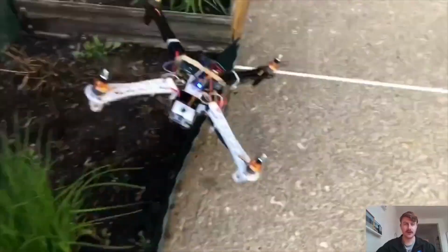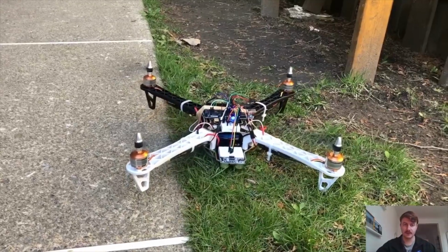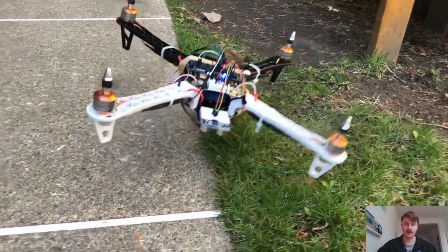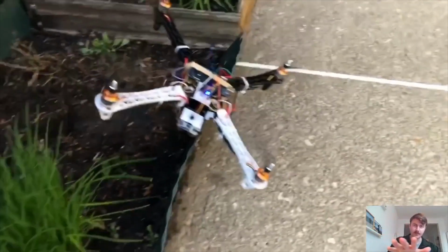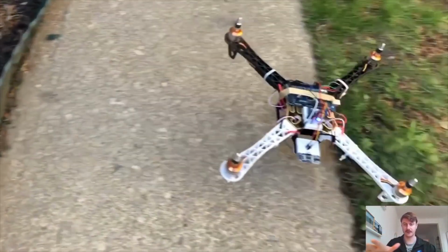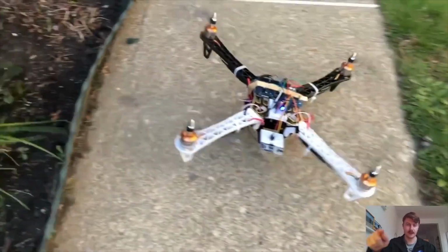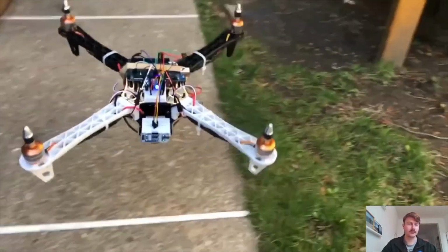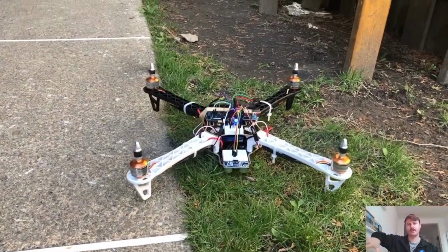Now this flight, I actually think is probably the best example of the control algorithm, because even though the real time looks fairly unstable, you see in the slow-mo that it takes off. It's a little unstable, so there's the P part of the PID controller taking action, and now it's stable, but it's drifting a little bit, so it sees that it's drifting and starts to correct the drift, but then it catches its foot on the ground and ultimately spins out. But if you see that catch of the foot is really what spins it out overall, and I think if it had a little bit more space, it could have come about and corrected that drift.